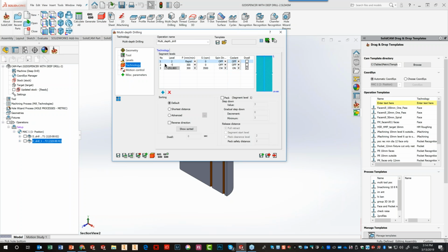Okay, my next step, after my minus 5, I'm going to go now to minus 99, about 1 millimeter above where I drilled down before too. Okay? I'll have my spin rate go on now. I'll put on a feed rate of, say, 1,000. I'm bold. And I'll put my coolant on. Some people, I've noticed, when they're going down in that first area over there, they actually like working counterclockwise. So I'll actually start this off counterclockwise up until I get to that point.